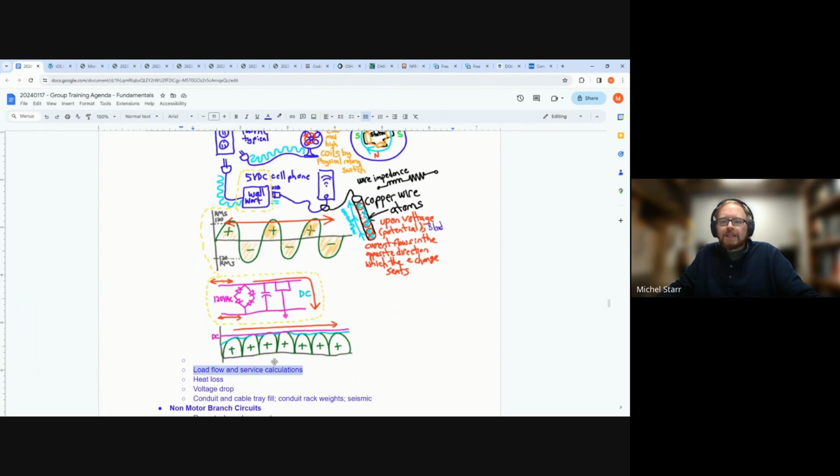Load flow would be as such, and we described the panel schedules quite a bit already, I think. So I'm going to note, other than that, they accumulate up to the service. You plug something into a panel board, then that panel board gets plugged into a distribution panel, and that distribution panel gets plugged into our motor control center, and all of the loads and the demand factors stack, which is the electrical code. Chapter 2 really goes through that.